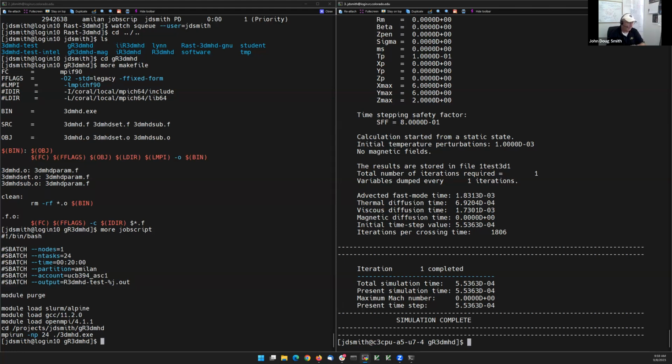If you do have a profiler, it may be worth looking at the memory to processor profile. It's pretty thin. You shouldn't have an issue with any of the cluster hardware that I've seen presented in the proposals. But that is another area where, if you really try to stack this densely, you may run into memory issues with trying to run other simulations at the same time as this on the same node. So your RAM per process, you may want to watch that and see if there's an optimal spot for your machine.